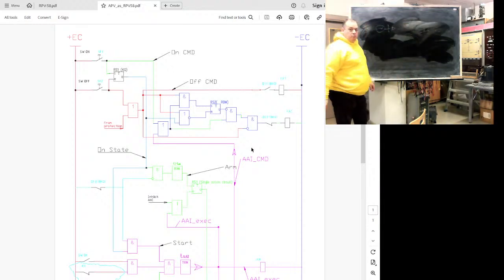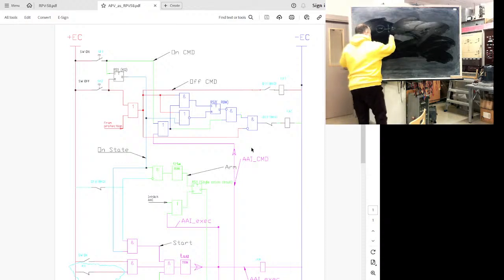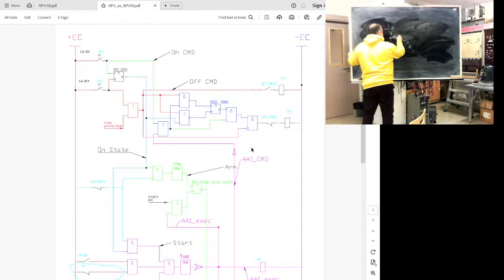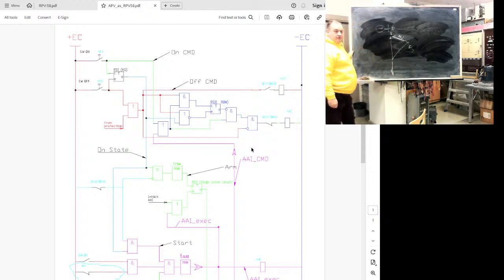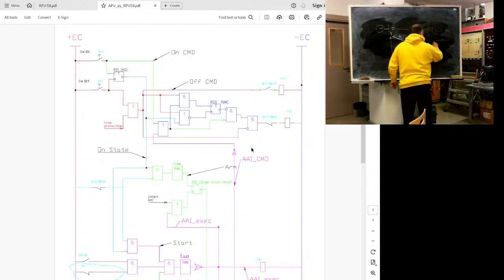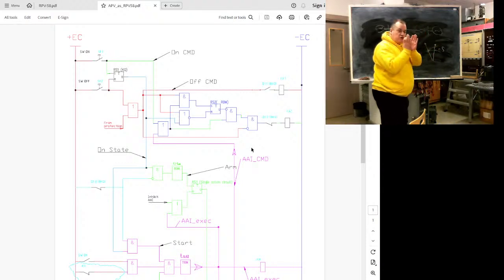If we have sources on both sides, it's possible that we will do reclosing when, in the worst case, they are 180 degrees apart. But anyway, this voltage difference will make us a problem. It will be serious heat. That means there is an allowable range when we can connect two systems safely.